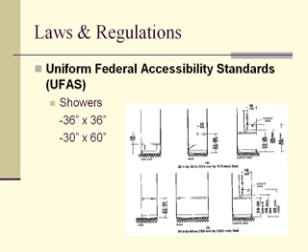Now, in the showers, they also have to have grab bars, again mounted between 33 to 36 inches above the finished floor. As you can see, the transfer shower has to be 36 by 36 inches and has to have the grab bar on the control wall and on the side wall to allow somebody to hold it and be able to transfer onto the seat. That transfer shower, the one indicated on top, has a seat which should be mounted at 18 inches above the finished floor so somebody can transfer onto it.